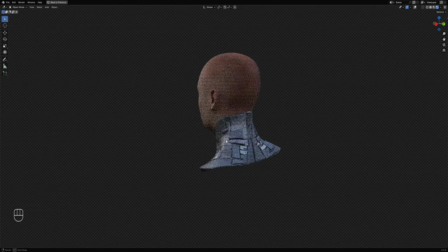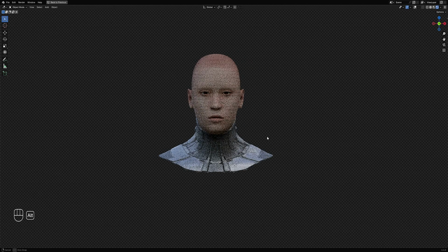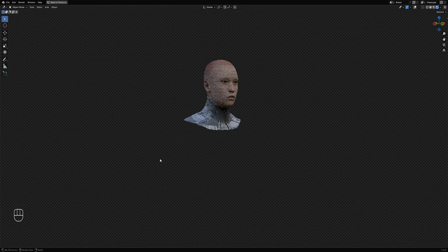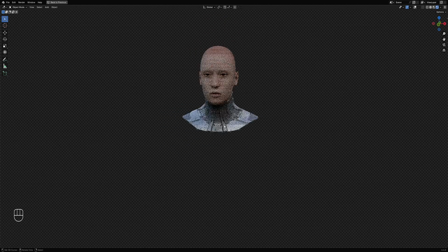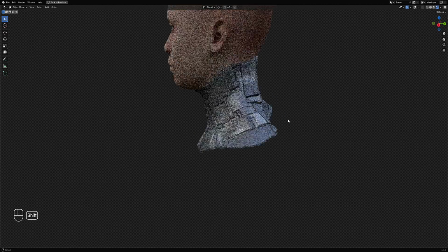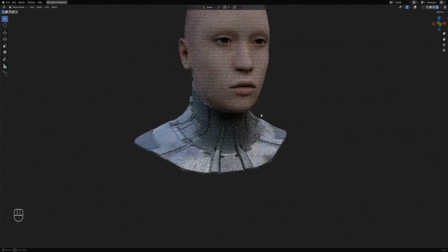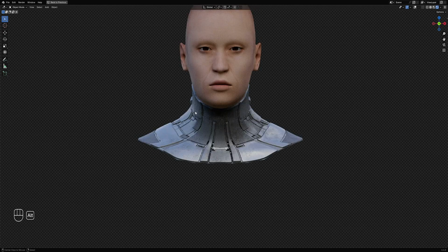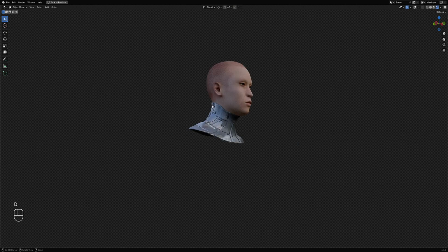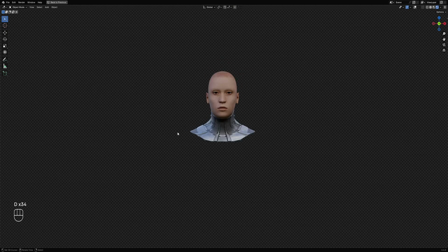It's up to you to add more texture to this. And if this was a whole body, you do the same workflow for the entire body, and don't do too much height on the depth, so you can just bake the detail directly using the base topology, the base mesh. You can just duplicate it and then create a Bake to Object from that.